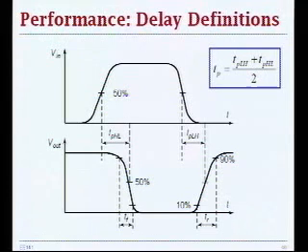There are also other parameters that factor into this delay formula that we'll talk about in much more detail, but just to introduce the concept here, apparently if you have more fan-out loading, it will take longer, right? Because you need to deliver current to more inputs, to more load. For that reason, we also define these rise and fall times.